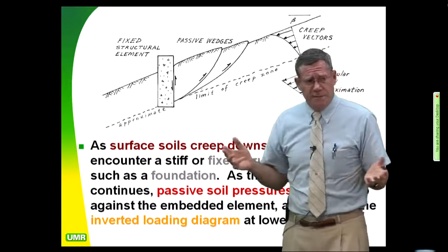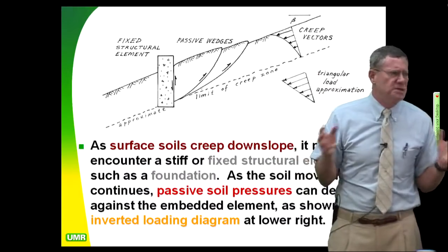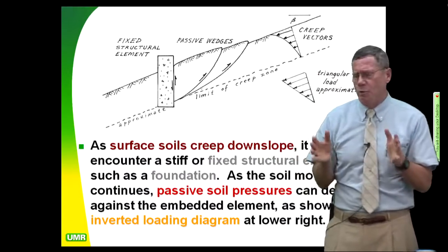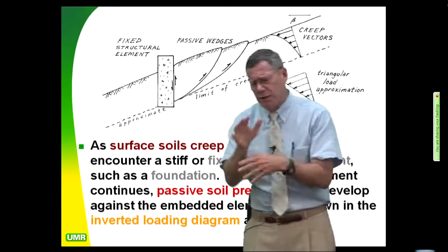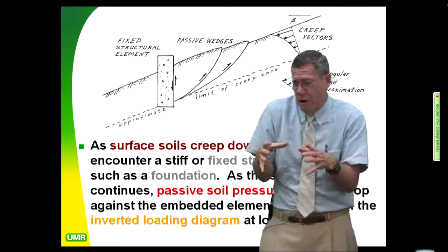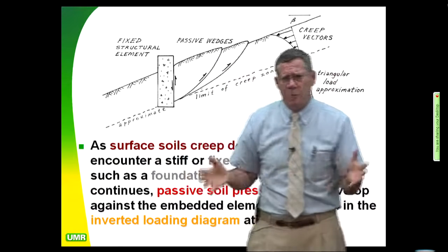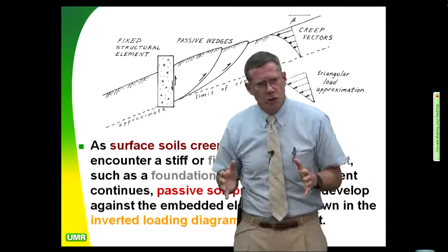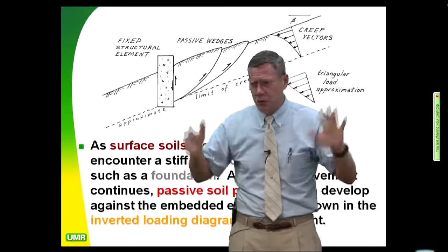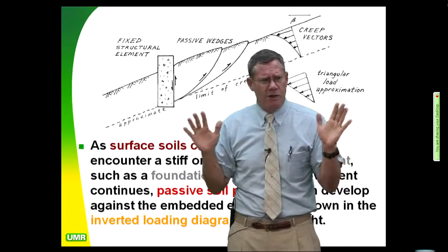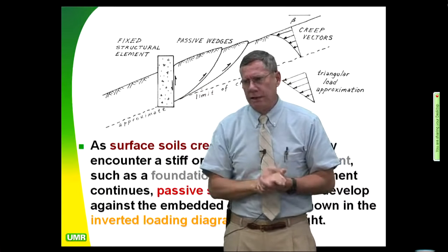Now, have I used masonry block? All the time. I use speed block all the time, where I'm going underground and I have to do a mine closure or something. I have to have small blocks and I have to get them in there, and where I'm keeping it in compression. Great for compression. It's okay. Not good for bending. Well, it's cheap.